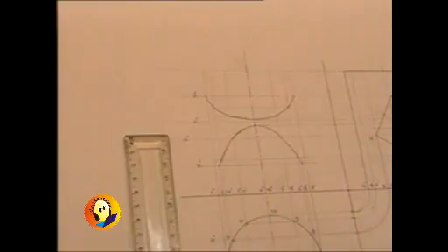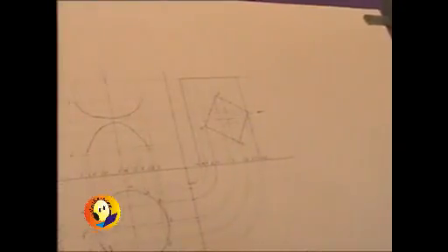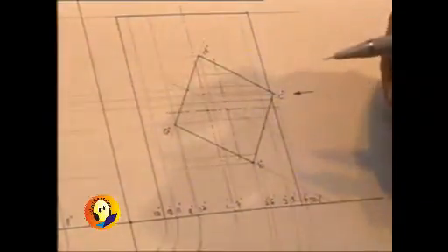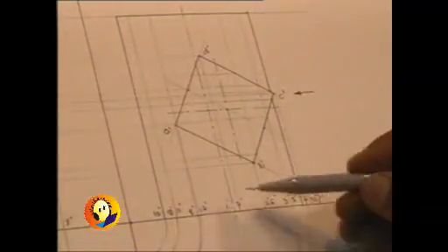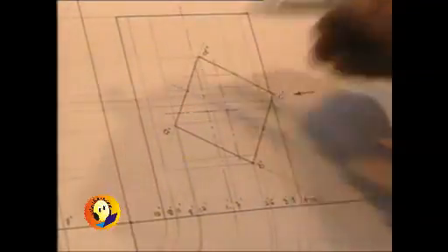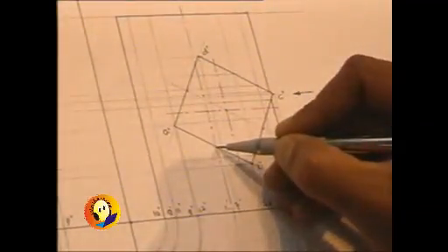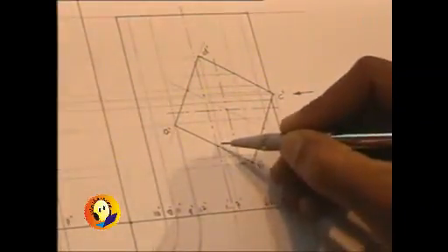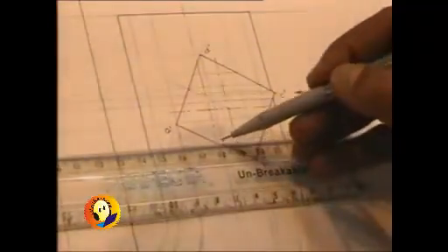Now for the top view, for the faces which are behind, namely face AB and face AD, we will have to carry out the same procedure. Observe that generator 1 and 7 is cut at these 2 points, and so we are required to take these 2 points to the front view.